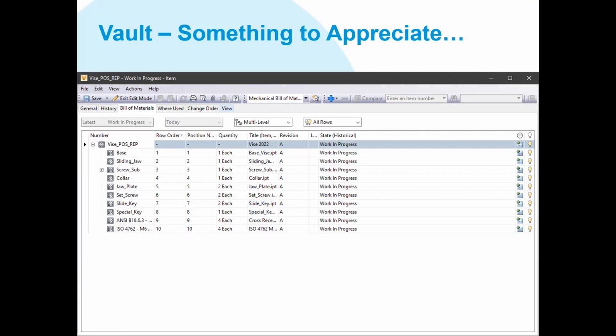When you put model states into Vault, there is only one file. So the M10 by 60 and the M10 by 50, they're not two different files. So Vault Basic will just say, I need whatever the file was set as master, an M10 by 50. It'll tell you the file that you need to make sure that you've got the IPT sat in your hard drive ready to be used. But not the instance of that file. But not the instance of that file, exactly.